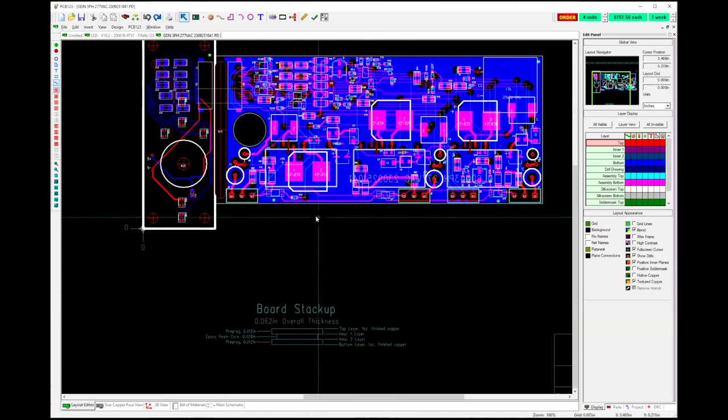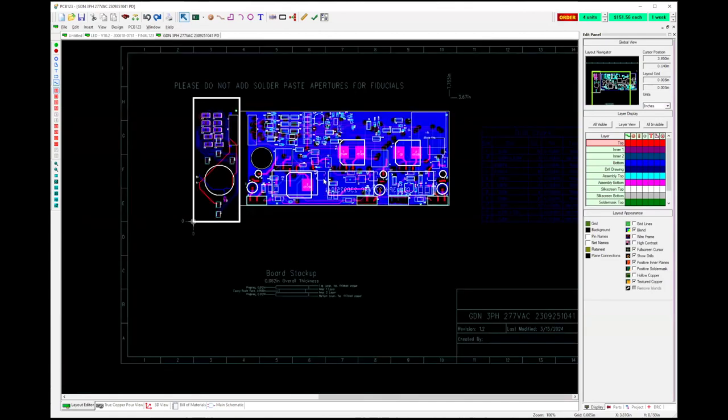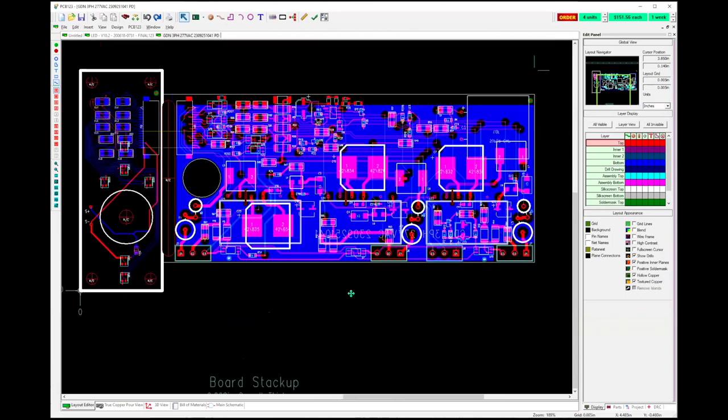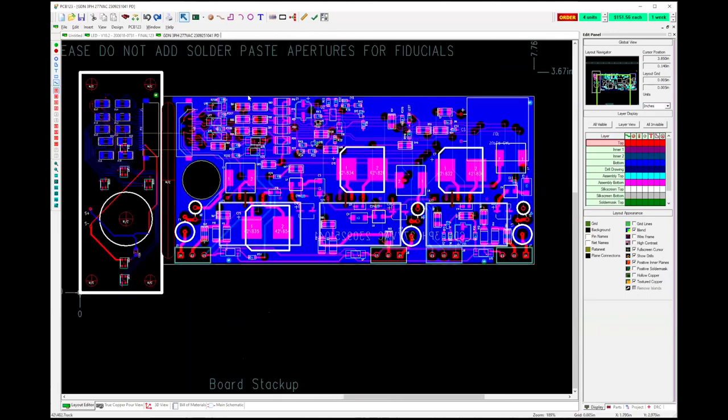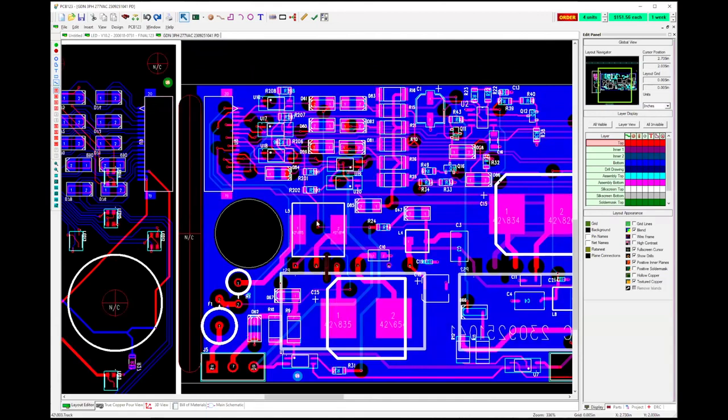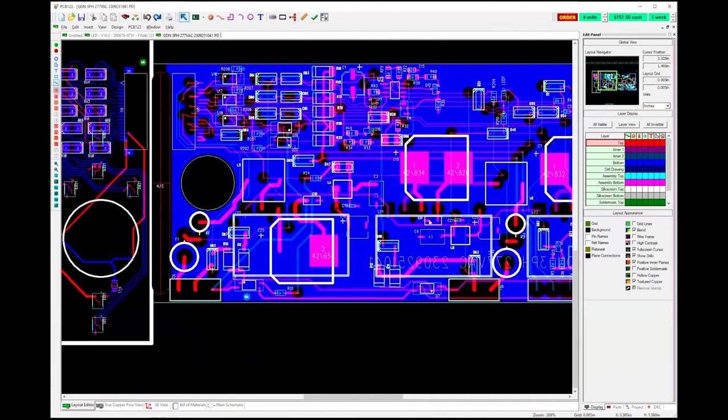Another feature that the tool has that's very nice is the ability to put in power planes and then route around them, so long as they're hooked up to the correct net and you get clearances that are appropriate. This is a pretty high voltage board, so I give it pretty large clearances around some of the wires to allow it to not arc or cause interference.